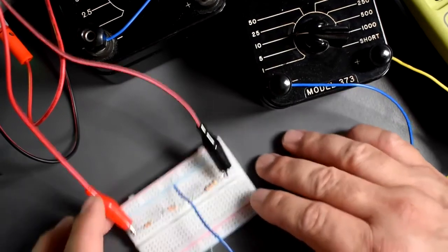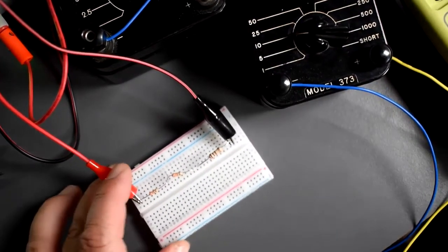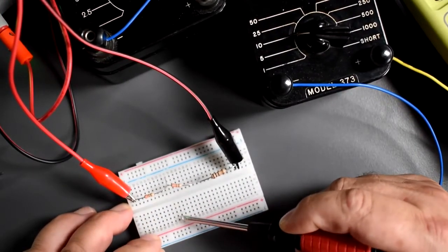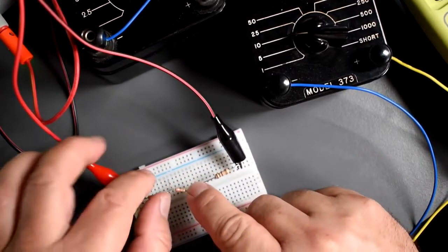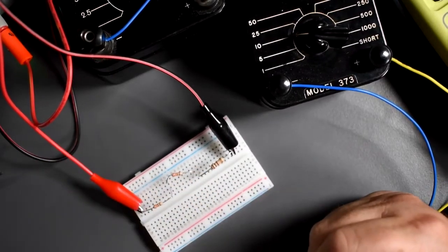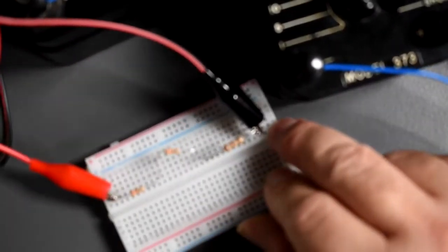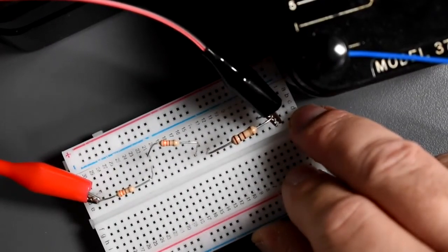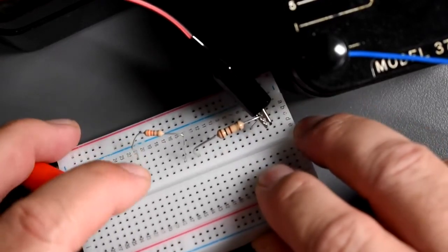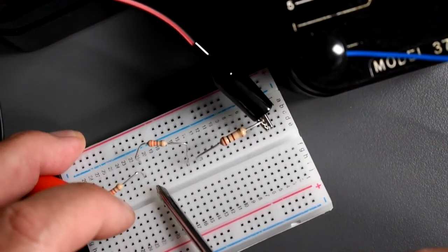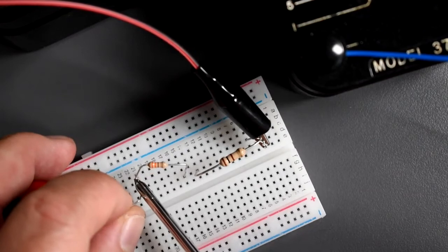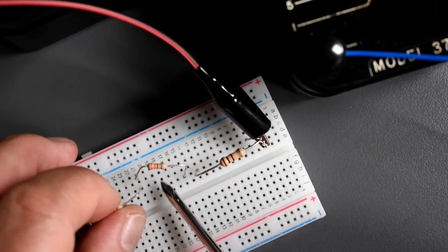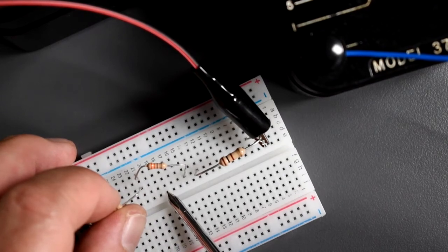So now we have 3 resistors. This is how the breadboard works. These lines here are connected. So when I put this resistor in this column right here, since vertically they're all connected, it's just like touching them like that. That's how the breadboard works. All of them are connected this way, but this column is not connected to that one. They're connected that way here.